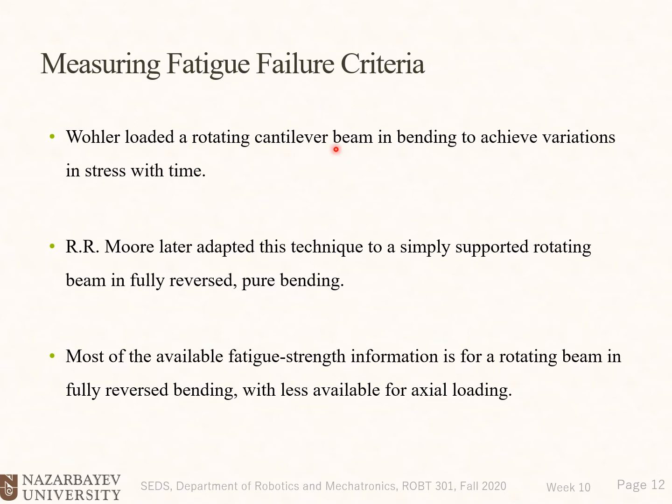Okay, so I suggest you pause here, think about the cantilever beam and the constant force at the tip, and think how a rotating beam could experience a fully reversed stress load. Why one specific point, let's say at the cross section or at the top fiber, at the fixed base, should experience that fully reversed stress.